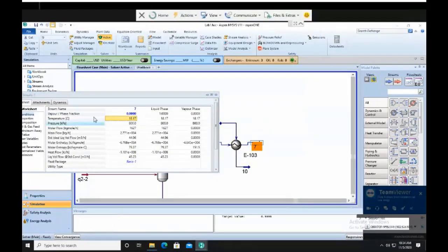So everything will be liquefied if the temperature is 18.17, but this is at saturated condition. So we do not want to set the temperature at 18.17. Remember, this one is to be stored in the tank before you send it to your client. So we do not want the change of pressure to evaporate the material. So you have to set the temperature lower than the saturation temperature.